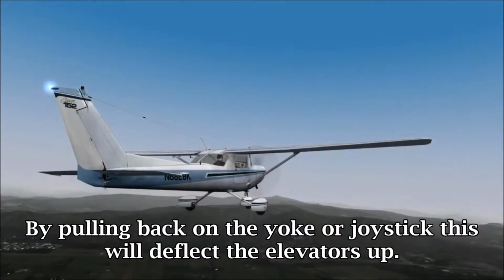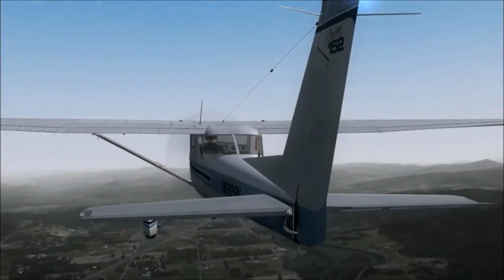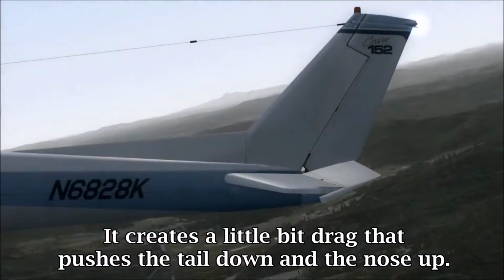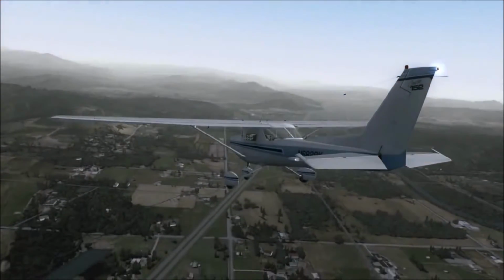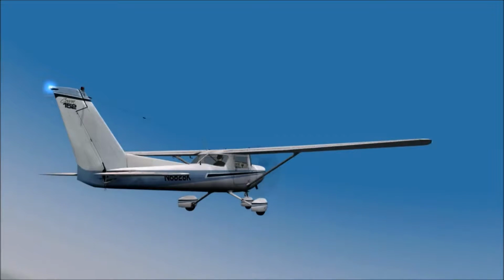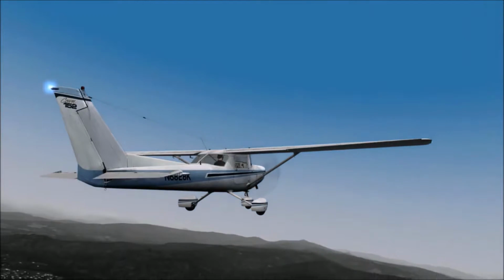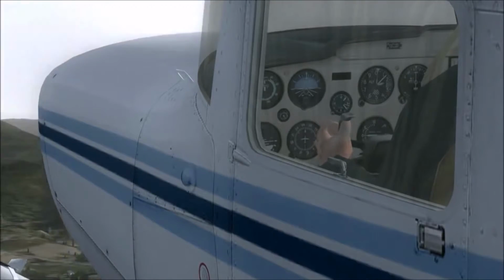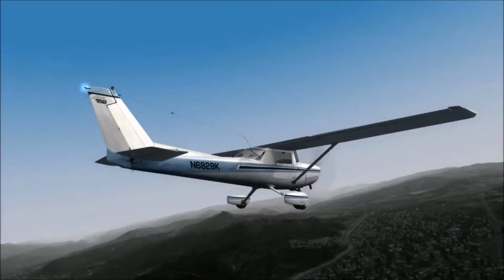By pulling back on the yoke or joystick, this will deflect the elevators up, like so, which creates a bit of drag to push the tail down and the nose up. Conversely, by pushing the nose forward, this deflects the elevators down. This changes the shape of the horizontal stabilizer into a camber that produces much more lift, pushing the tail up and the nose down. Remember, elevators change our pitch. Pull back, we go up. Push forward, we go down.